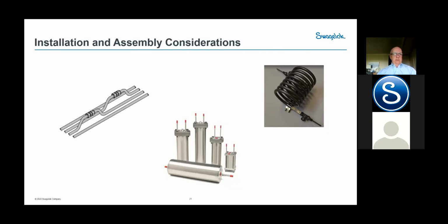Now, tube connectors are the third method that we prefer, and we use tube connectors all the time. It's an easy method to make the connection. They're guaranteed not to leak if the people are trained properly when they're putting them in. So there's no issues with it. So you have three choices. When it comes to sampling systems, tube connectors are the preferred method. Welding is probably number two, and we never typically use flanges.